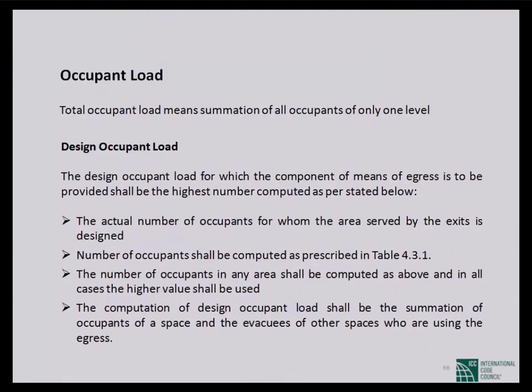Occupant load. The design occupant load for which each component of the means of egress is to be provided shall be the highest number of occupants as stated below. The actual number of occupants for whom the area served by the exit is designed. The number of occupants shall be computed as per the prescribed table 4.3.1. The number of occupants in an area shall be computed as above.